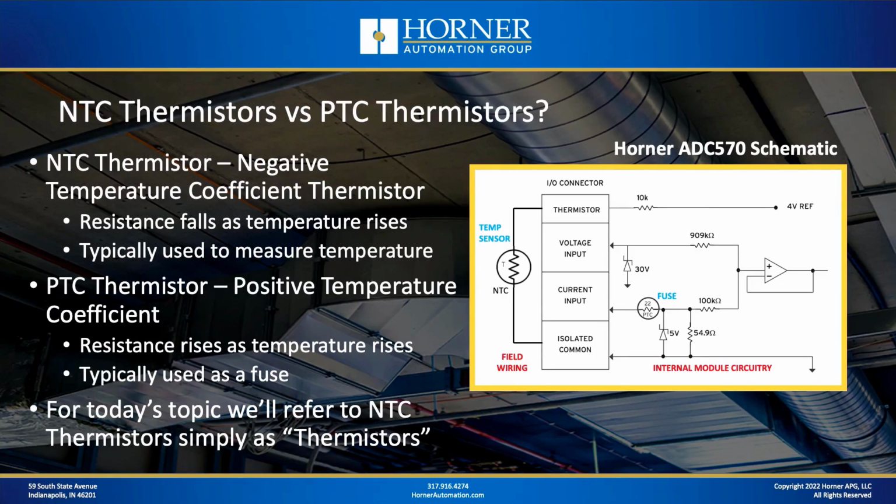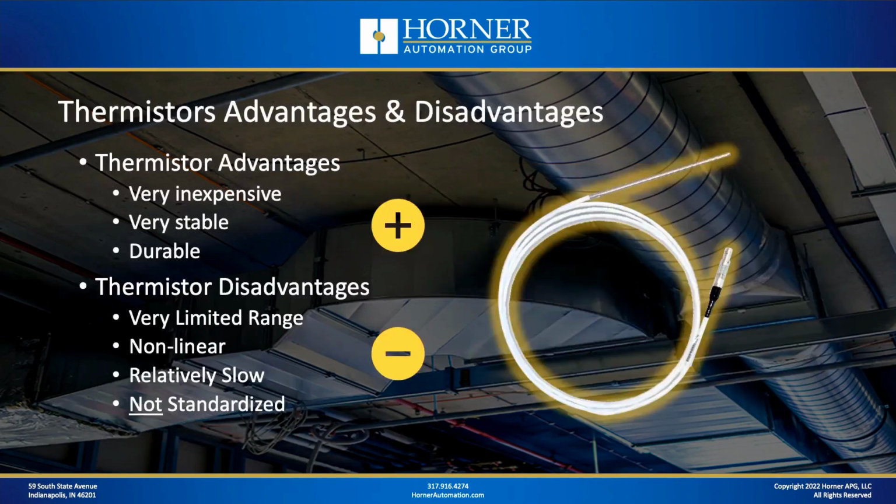Now, on the screen there, I'm showing a schematic of one of our Horner I/O modules that supports thermistors. And you can see on the far left there, we're showing an external wiring of a thermistor into the module for measurement purposes. And then, interestingly enough, on the right-hand side of the diagram, you can see in the internal module circuitry a PTC type thermistor that's being used as a fuse. So they're both very commonly used, but from an industrial standpoint, when it comes to temperature measurement, we're talking NTC thermistors.